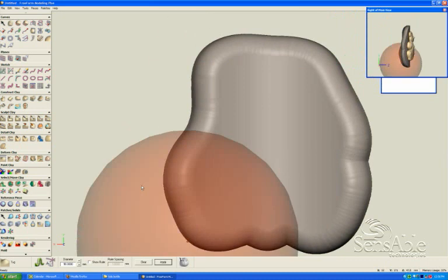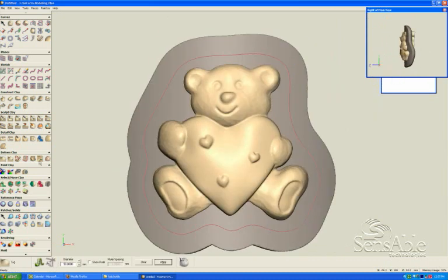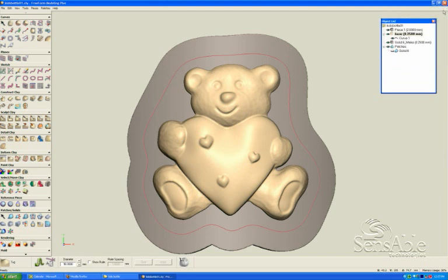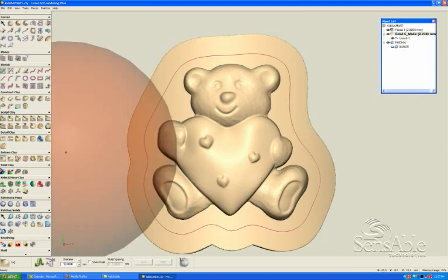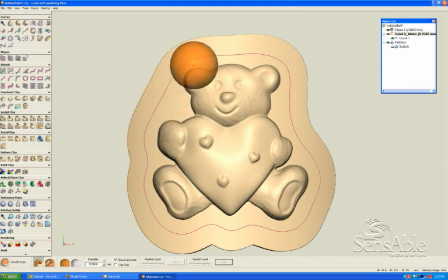Once that is completed, we can hit the apply button on the Dynabar, and that will apply those changes. Once we've done that, we want to combine the thickened part into the design of the bear so that we have one piece. We can do that easily through the combine into Boolean technique on the object list. That's a very simple function in FreeForm, as opposed to doing Booleaning and shelling in CAD, which can be very difficult and frustrating because of the innate problems with those functions with surface and solid data. But since we're working with a completely different geometry called voxels, those functions work very well in FreeForm.